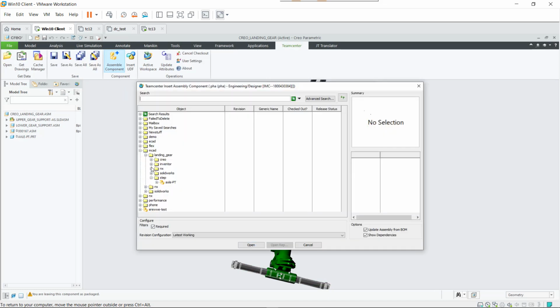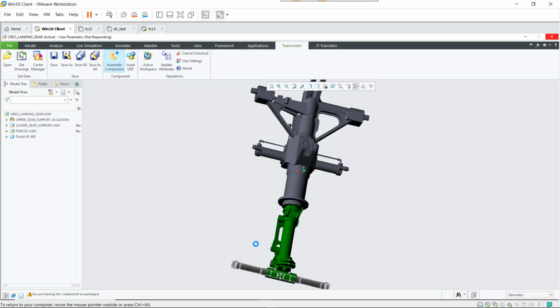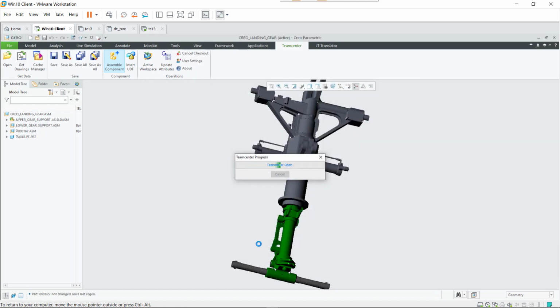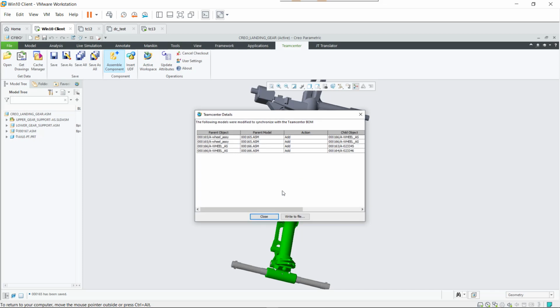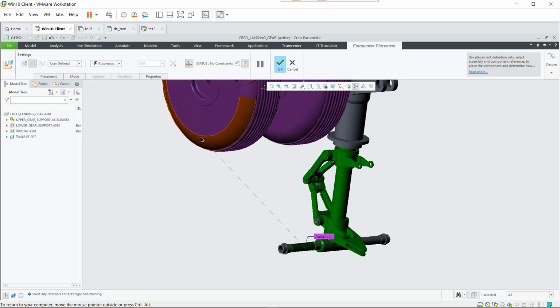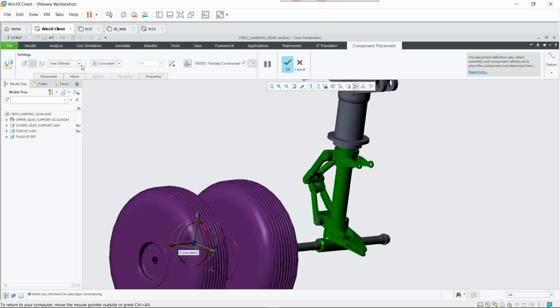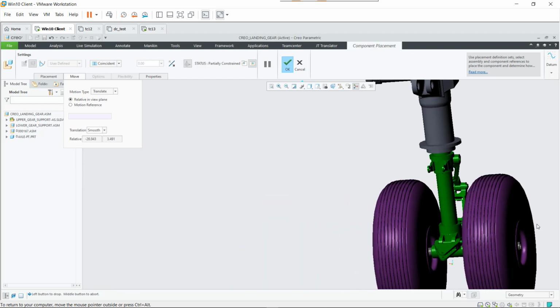Now we can complete our Creo design by adding the nose wheel assembly from NX. Remember that NX is configured for hybrid reuse. The Creo integration will download the NX part files, and will build the assembly using positional information from the NX design's bill of materials. With this technique, native Creo models can be constrained to the NX part files, but not to the dynamically constructed Creo assembly that represents the NX assembly.